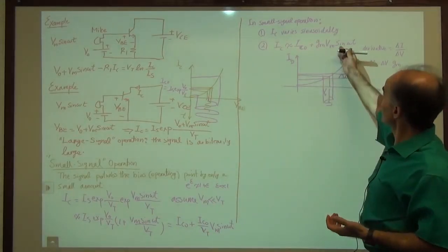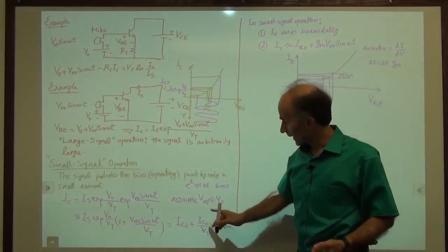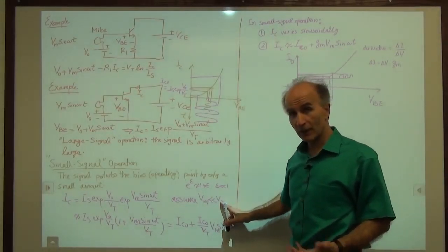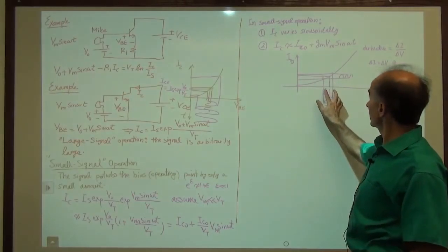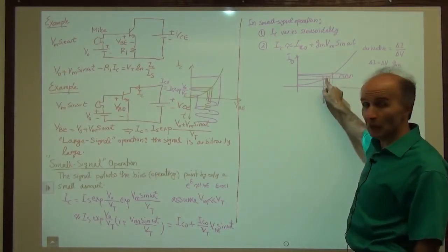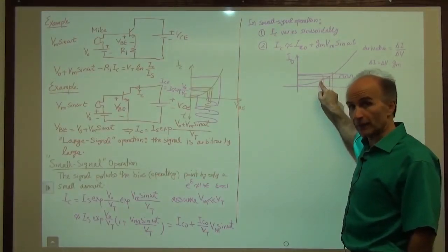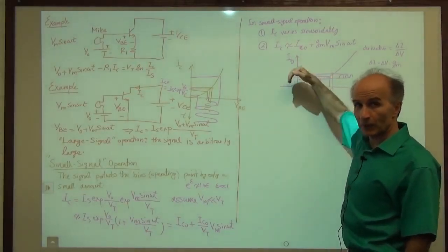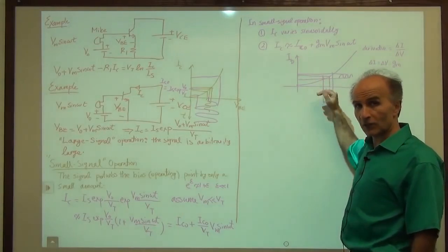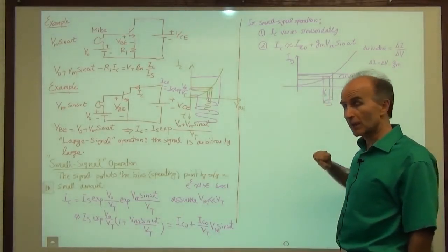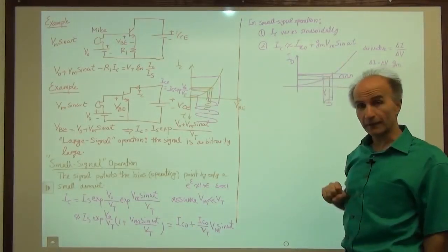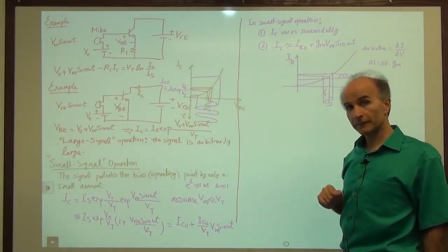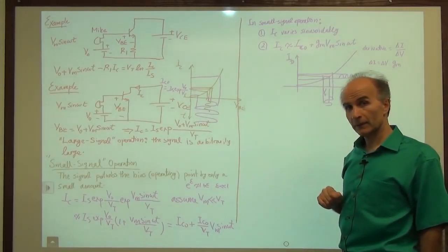And that makes perfect sense. When we assumed that Vm was much less than Vt, in a sense, we are so small in this variation that we are looking at the slope of the curve. And the slope of the curve is Gm, so obviously the input change times the slope gives us the output change. And that's why we ended up here. So that's nice. All right.